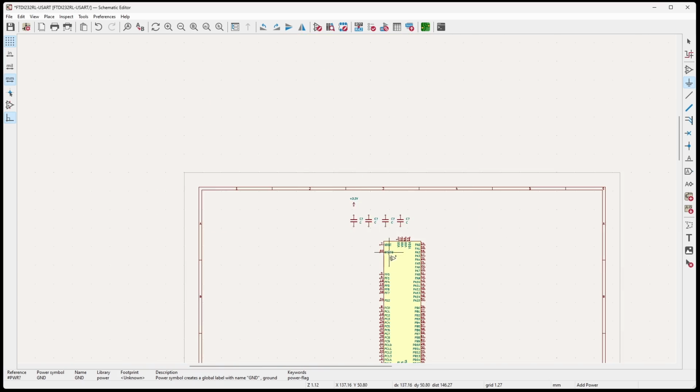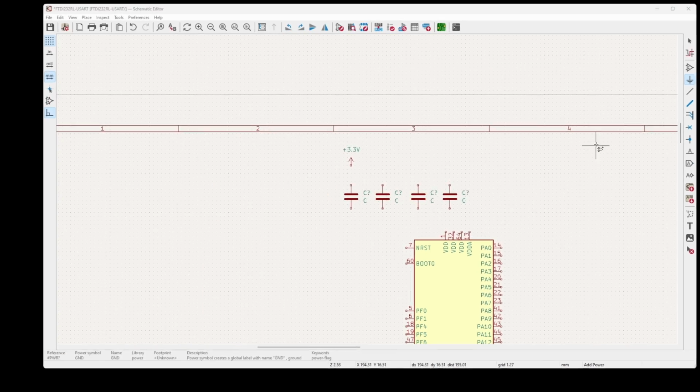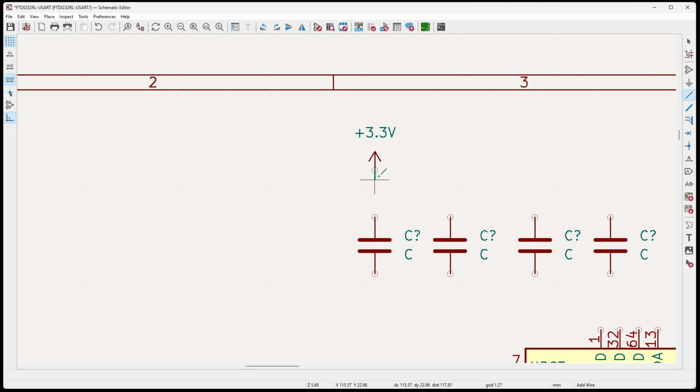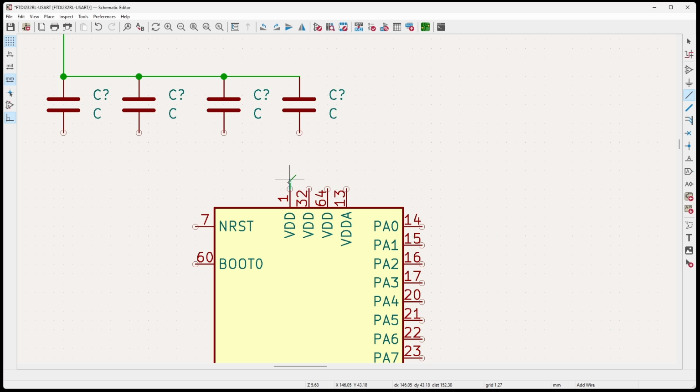So I'm going to start with the positive pins. The net or wire command is right here. So I'm just going to click on the little circle. That would be the origin for the symbol. Going to connect them together. I'm going to do the same thing with all of these, because all of these decoupling capacitors are going to connect to the positive 3.3 volts, and it's also going to connect to the ground. I'm going to connect all these together because that's the way we have it on the prototyping environment.